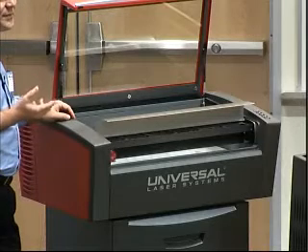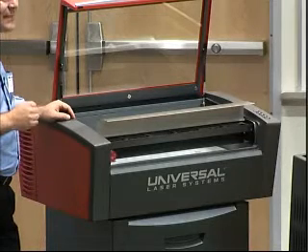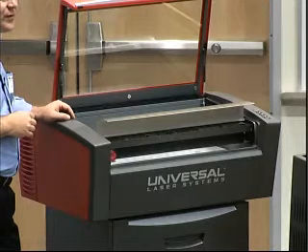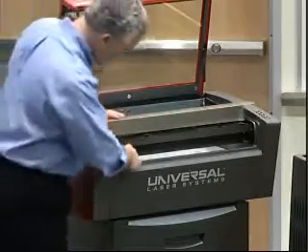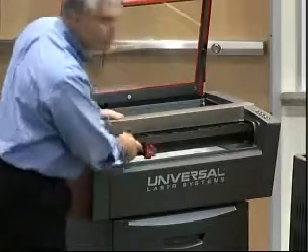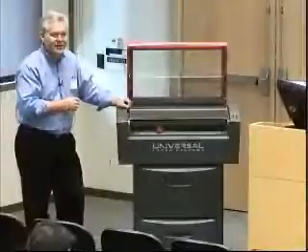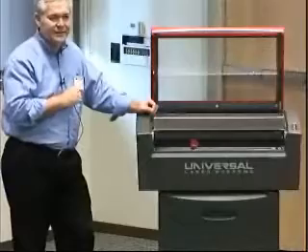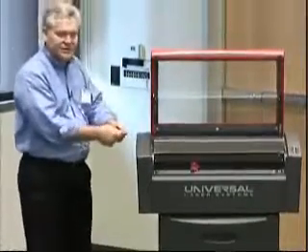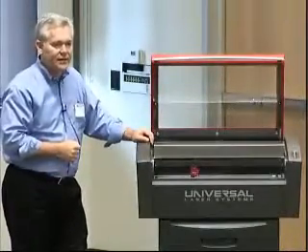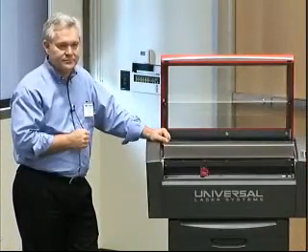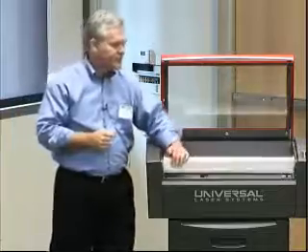Usually the problem is a beam alignment problem. And there's a beam alignment procedure that we can go through if you're not familiar with it. It essentially amounts to putting something over this hole, like just a piece of tape, and firing the beam and making sure that you're burning right through the center of it. Then there are adjustments to each of the mirrors, so you can adjust that so you're right in the center. But that's generally the problem.